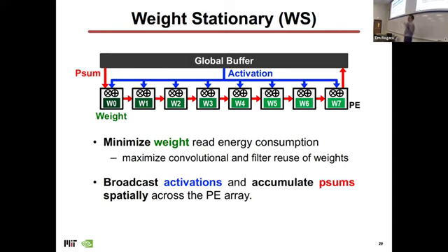You can think of it like an FPGA being programmed, right? FPGAs are programmed with bitstreams. You take your design, take your RTL, and compile it down to a netlist, and then eventually it becomes a bunch of ones and zeros that get shoved across some interface to your FPGA that say whether each gate should be programmed on or off, or this connection should be made or whatever. It's sort of like that. And so there'll be some software layers in between that allow that kind of programmability.